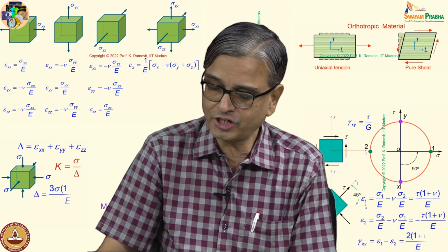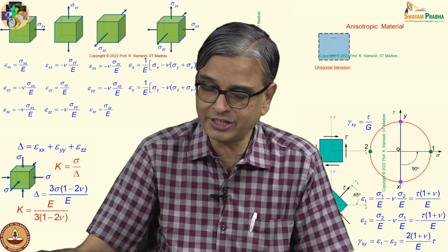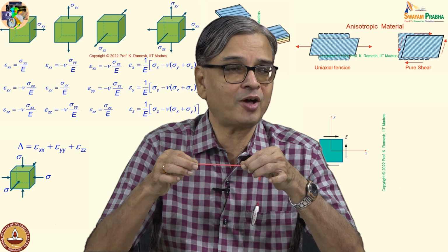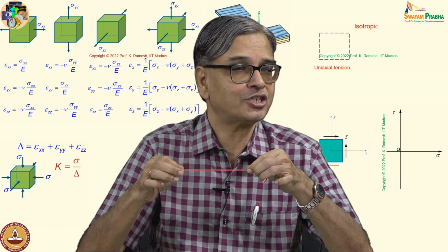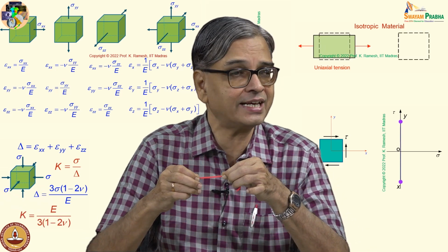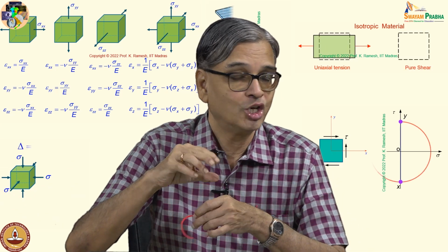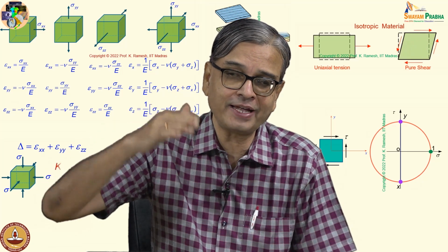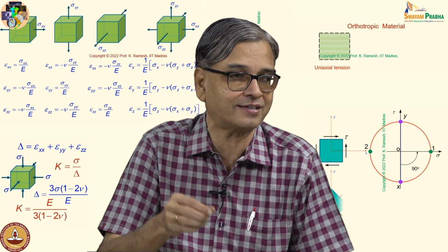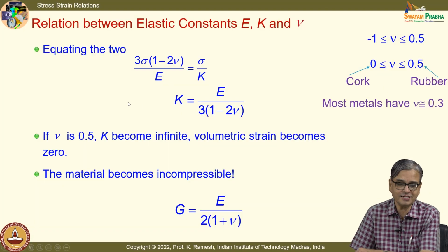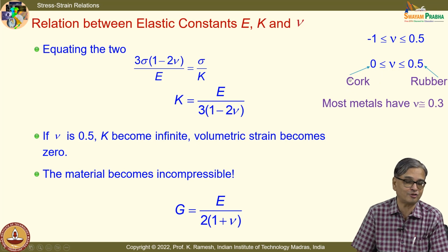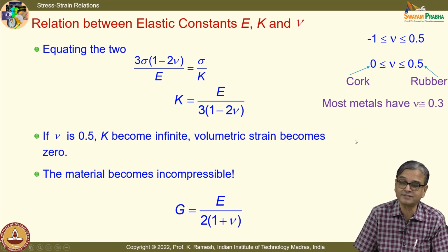Normally, when you look at Poisson ratio, we imagine that when I stretch, the lateral part gets opposite strain. When I stretch it, it shrinks; when I compress it, it can bulge out. So, if you are sealing a bottle and applying a compressive force, if it bulges out, it will be difficult for you to insert it. That is one of the advantages. Another advantage is that it also allows oxygen into the bottle. That is one of the reasons.